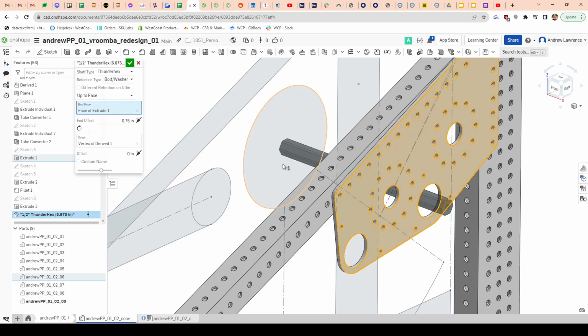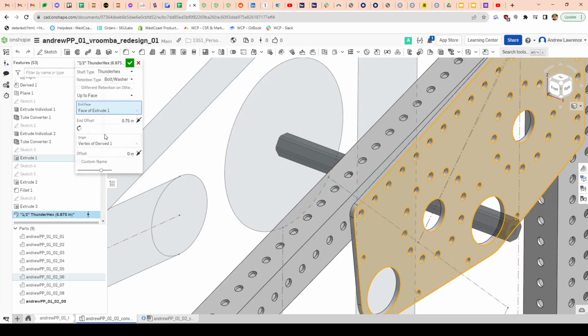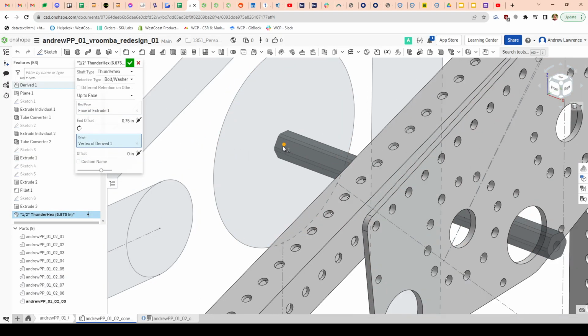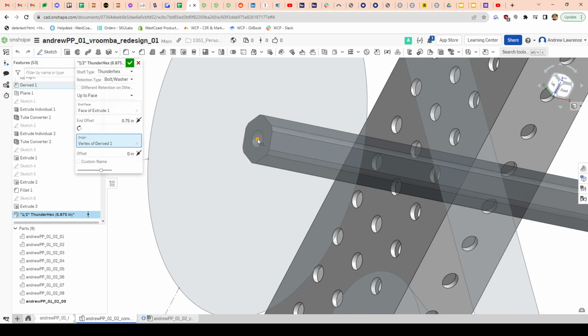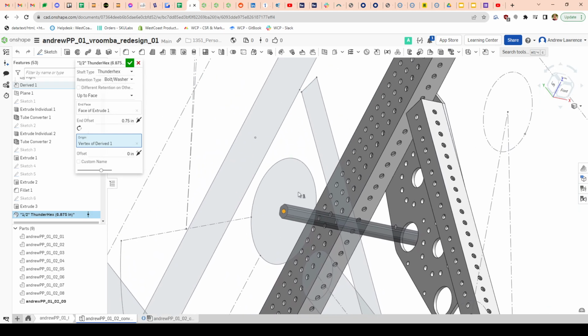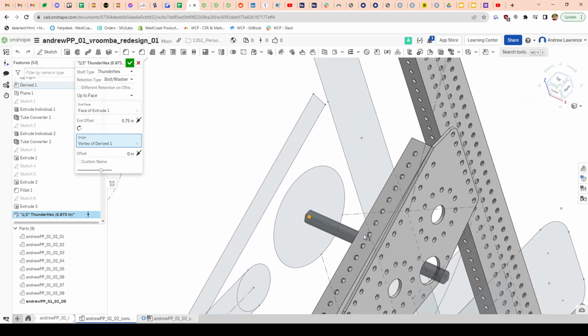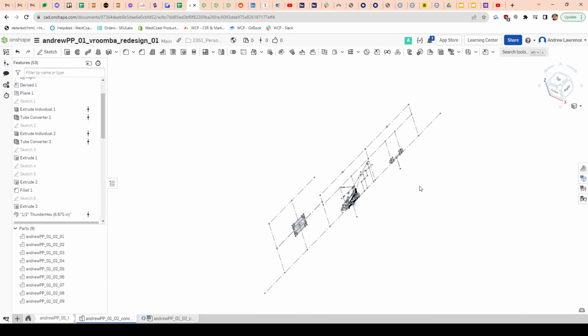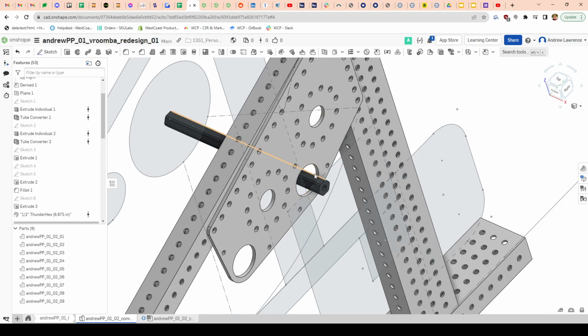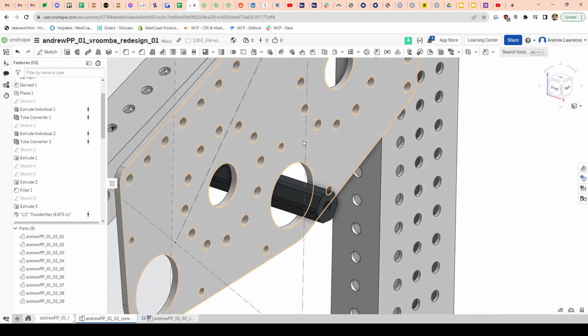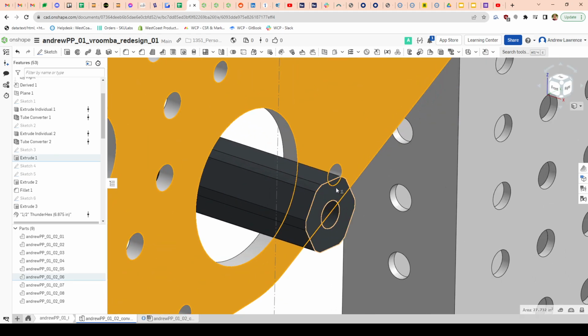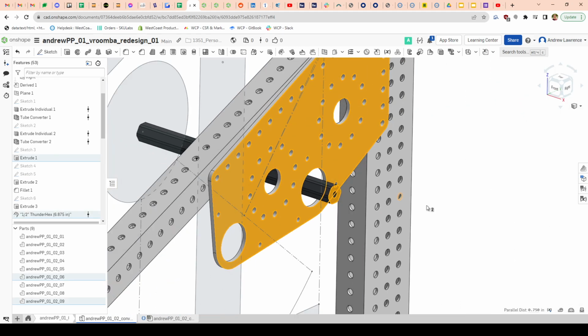So when I went to my shaft generator, my origin was the vertex point, the center point of my shooter wheel sketch. So it was that point right there. Sorry about that. So it was the center point of that right there. And then the end point was a 3/4 inch offset from this plate, from this face.